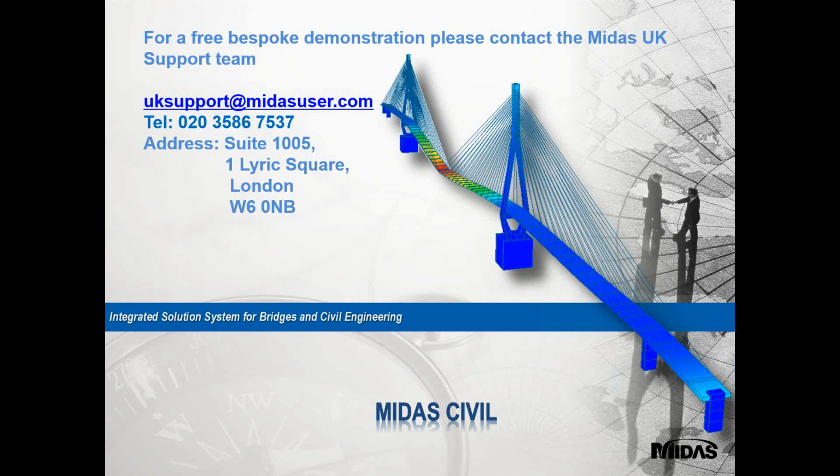And the deformations are applied on the nodes of each element. So as long as you have modeled all the elements of your structure, you should have all the deformations incorporated. All the local deformations, local cross girder deformation, or let's say main girder global deformations, they all are incorporated in the final updated model.